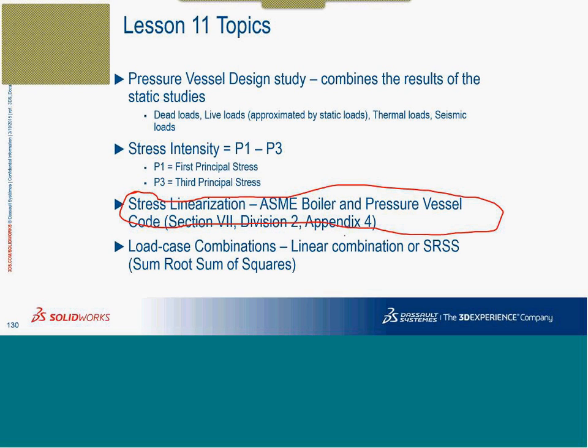This is a post-processing option, just like fatigue analysis. So we need to do the other different analyses first. Thereon, we can take the results from those studies and do stress linearization. That is it. Typically the question you face is: do we have something customized for pressure vessels, or is it customized for the pressure vessel industry?